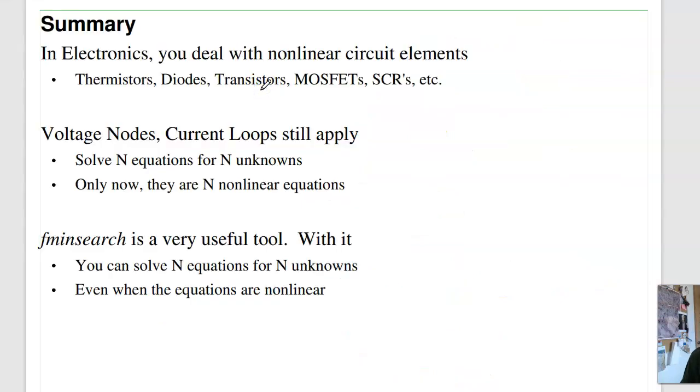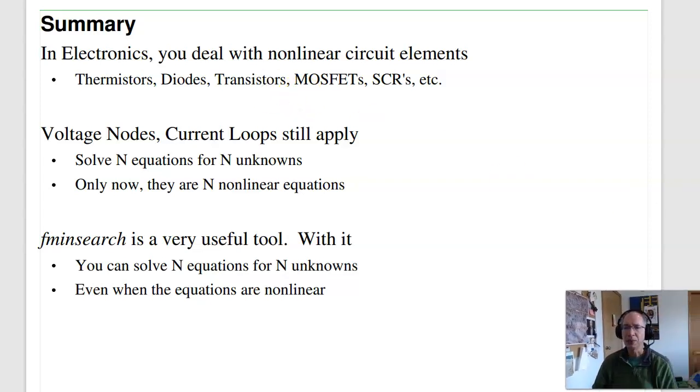So in summary, in electronics, you deal with nonlinear circuit elements: thermistors, diodes, transistors, MOSFETs, semiconductor relays, and so on. Voltage nodes and current loops still apply. Using voltage nodes and current loops, I can write n equations for n unknowns. However, they're going to be nonlinear equations. To solve nonlinear equations, fminsearch is really useful.